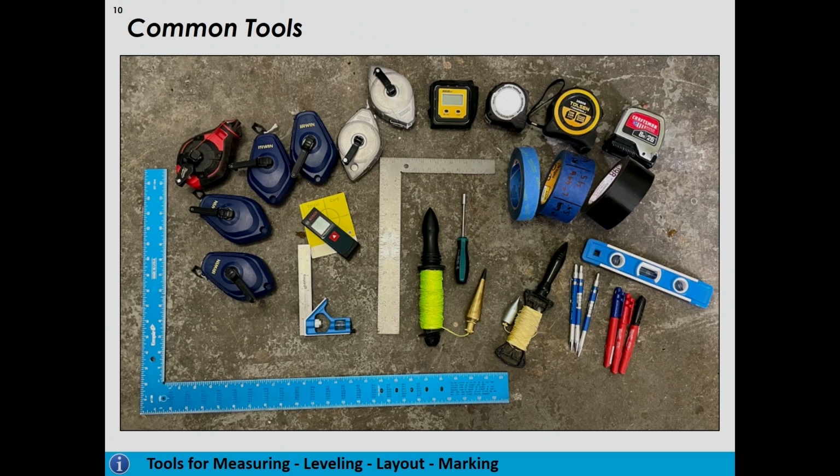The manufacturer is going to tell us how we have to do that. Many times we're going to drop a plumb bob at the center of the front of the vehicle. They'll tell us where that measurement needs to be taken, and also the center of the rear. We're now going to have to create a straight line from one point to the other, and we're going to show in some slides how we actually do that too.